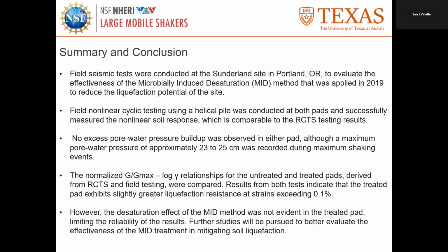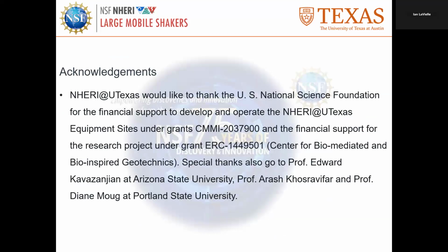We saw the treated pad exhibit slightly greater liquefaction resistance after the strain exceeded about 0.1%. However, the desaturation effect of the MID method was not evident in the treated pad, so there's some limitation to the reliability of the result. Further study needs to be pursued. That's the reason Diane did a retreatment, and we tested it; they should do some testing last week. So I hope that we can have more understanding of soil nonlinear behavior in the future.